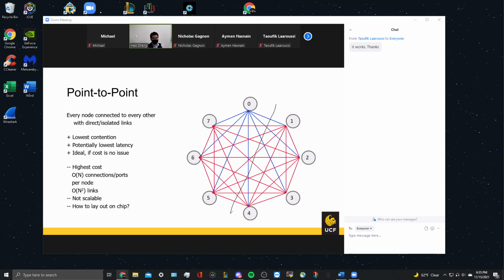So you basically just cut and count how many links across this line, right? There are lots of connections, which means the bisection bandwidth is much larger than the previous one. Do you know what I mean? Cut the entire network into two halves and check how many lines cross: 1, 2, 3, 4, 5, 6, 7, 8, 9, right? Count how many links cross this line, and you will get the bisection bandwidth.